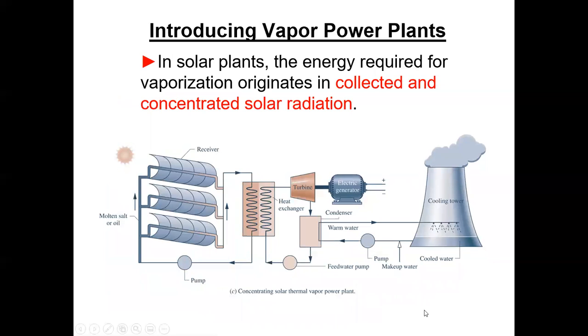And then we can go on, and we can look at what is called a concentrating solar system, power tower. What they usually have is a bunch of mirrors on the ground, like in a semicircle around this tower. On the top of the tower, they have the boiler sets, and these individual mirrors on the ground actually track the sun in their program. So they continually focus the maximum amount of solar radiation on that boiler up on top of the tower.